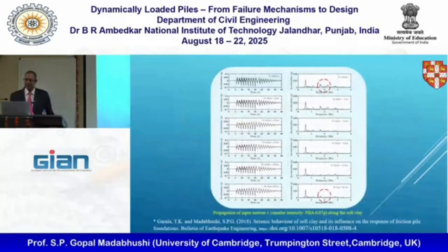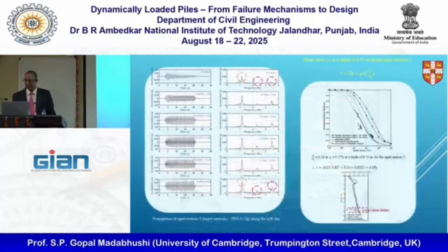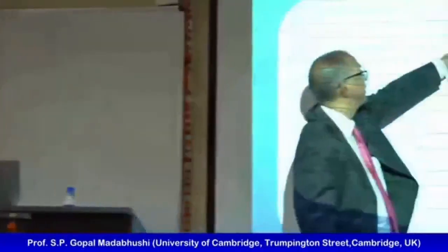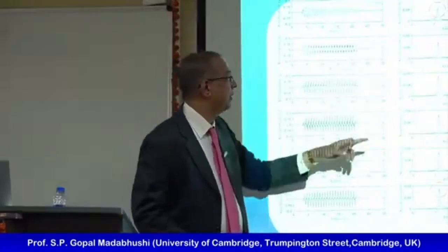But the interesting thing was that we could see how the accelerations change as they go through the clay. Some components get bigger and some components get smaller. By the way, this work was done with the SAM actuator, so we didn't have the servo-hydraulic actuator right then. He used it later on. And what we could see is that for bigger earthquakes, these high frequency components are disappearing. So clay is acting as a nice filter, getting rid of high frequency components which are there at the bottom but not at the top of the clay.